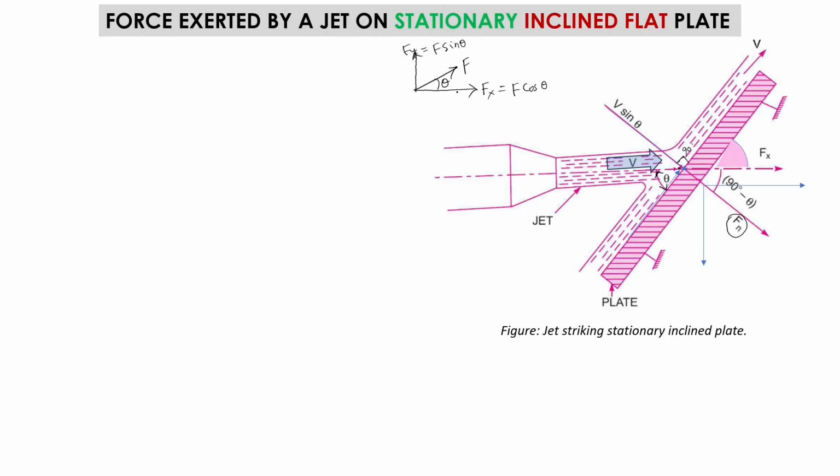So this is the easy way to remember: for the component we want to figure out, if the angle is with that component, you always consider cos, and if there is no angle with it, you can write sine. For example, I can show it like this, just for those who may have missed this. If this theta, the angle of inclination, is with this, then Fy is F cos theta, and Fx is F sin theta.